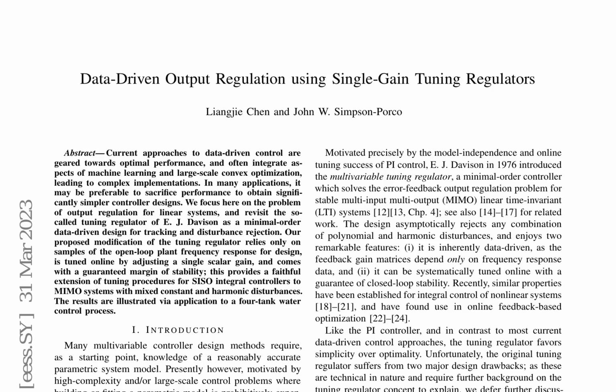The paper then presents the multivariable tuning regulator proposed by Davison, which aims to mirror these characteristics in the MIMO LTI case for more general reference and disturbance signals generated by the exosystem. The design procedure involves defining the exogenous input signals and requiring an integral controller with specific properties. The paper concludes by emphasizing the need for satisfactory performance, which may require additional stabilizing precompensation before tuning the integral loop.